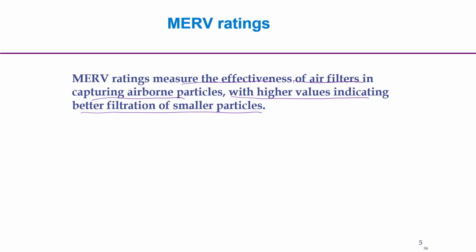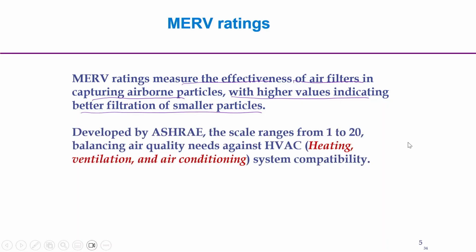A lower value means it will capture the larger particles effectively, but a higher MERV rating means it will capture the smaller particles, and obviously the larger particles also. It was developed by ASHRAE, and the scale ranges from 1 to 20, balancing the air quality need against the HVAC, that is heating, ventilation and air conditioning, system.